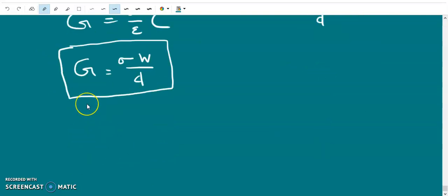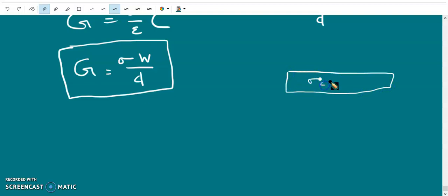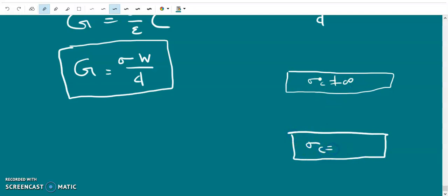So now we can calculate the resistance per unit length of the conducting plates. So we have seen that the conducting plates are having a very large value of conductivity, but it is not infinity. So they are not perfect conductors. So there will be losses due to these conductors also. Losses may arise due to two reasons. One is due to the non-vanishing loss tangent, and the other is due to the imperfect conducting plates.